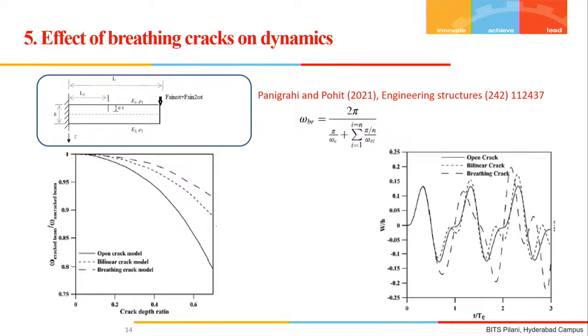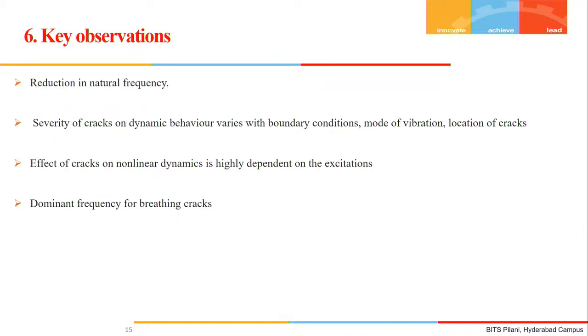So this is what I wanted to tell about how cracks affect the dynamics of beams, and there are so many things to take away for structural engineers. More or less what we have discussed, the key observation is the reduction in the natural frequency. That is a very key fact: whenever there is a crack or a flaw, because of the induction of local flexibility, the natural frequency will reduce. That is a sure shot phenomenon that is going to happen.